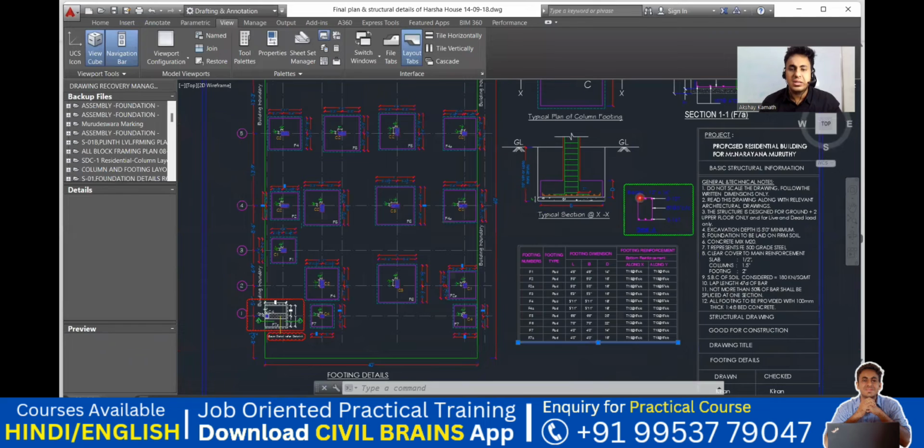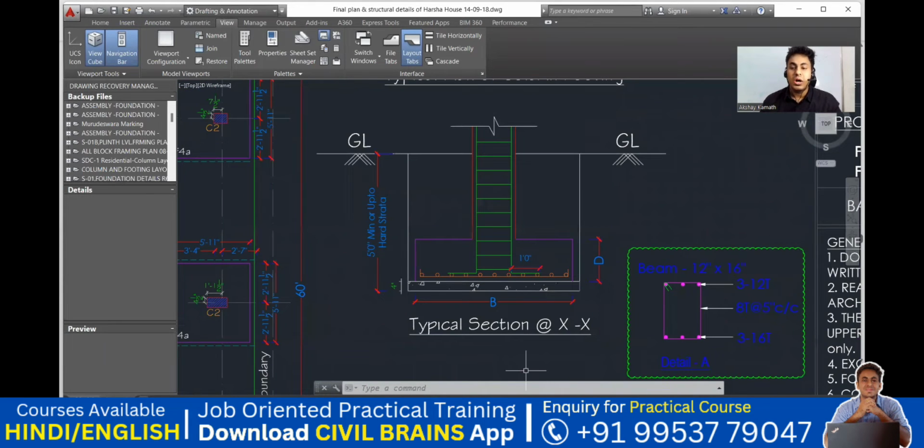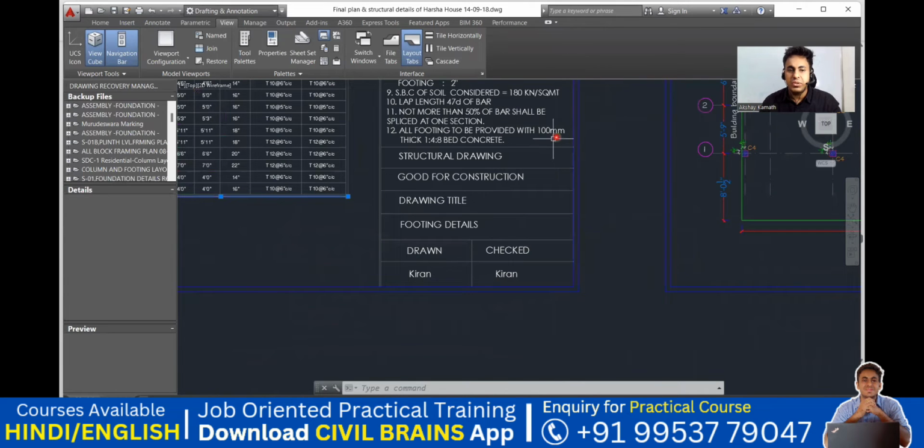And now coming to the excavation part. This is a typical cross section they give. How much excavation are you supposed to do? It is mentioned here. Right now, you're standing at the ground level, and you excavate from the ground level to the bottom of your PCC. This is my PCC, which is 4 inches, coming out to be 100 mm. That was mentioned here: all footings to be provided with 100 mm thick bed concrete.